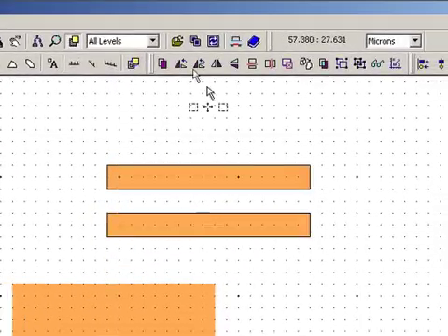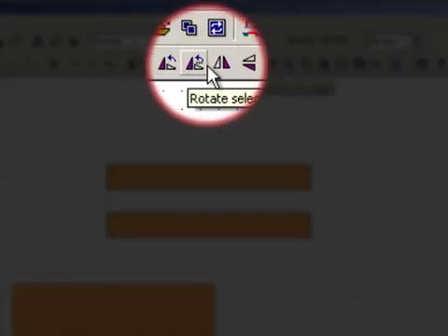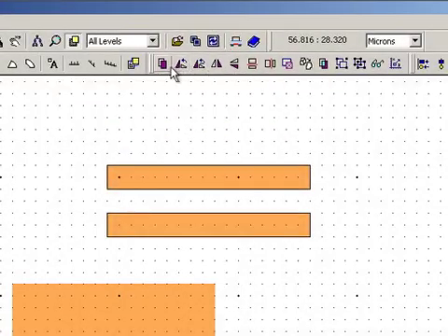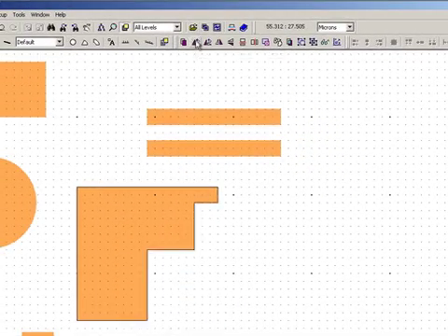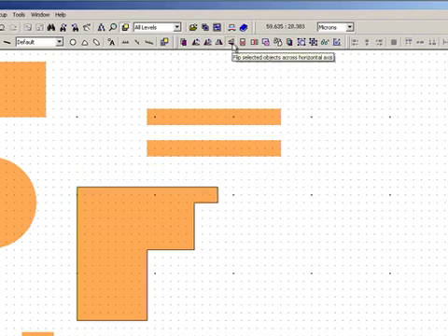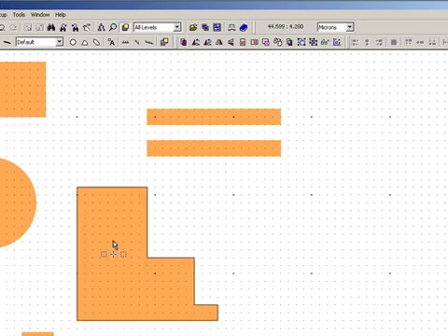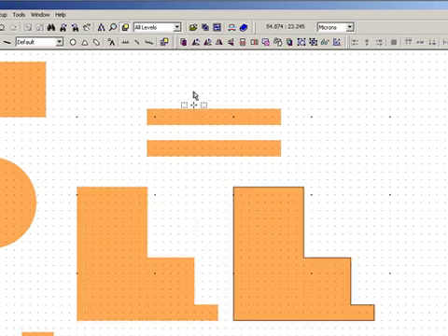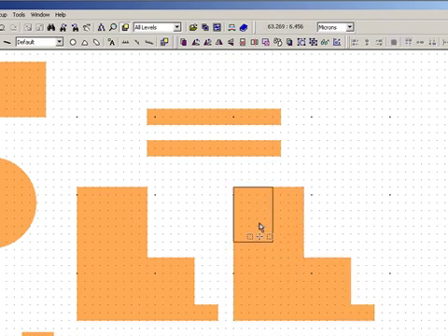Alright, the next group of icons we have here, starting from here over to here, is basically for flipping, duplicating, rotating any of your shapes. So if I have a shape here, I can mirror it, flip it horizontally, arbitrarily, some random angle. I can also flip vertically or duplicate it, which would be the same as hitting Control-C, Control-V. I can also slice my polygons using the little slicer tools here. You can slice horizontally or vertically. So this basically breaks this polygon up into a number of smaller polygons that I can manipulate individually.